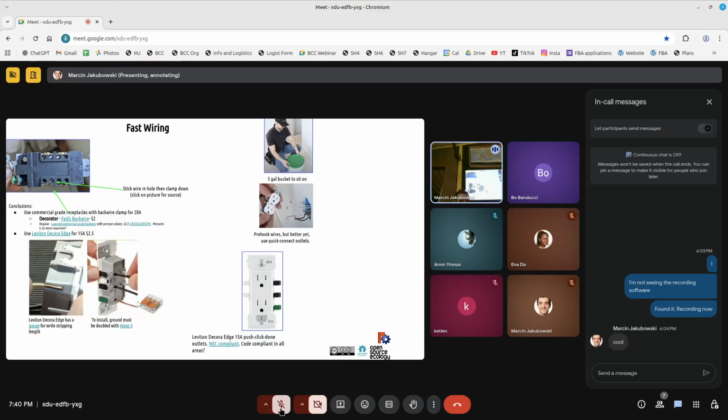Would you ever put that pipe in the ceilings so the cool would come down? Yeah, absolutely. I think you'd want to have heating in the ground because it rises, and cooling in the ceiling, if you're doing a hydronic kind of thing. Have you ever tried solar heating with floor heating? Haven't done that. That's a great thing to do. I mean, solar thermal is great. Mm-hmm.